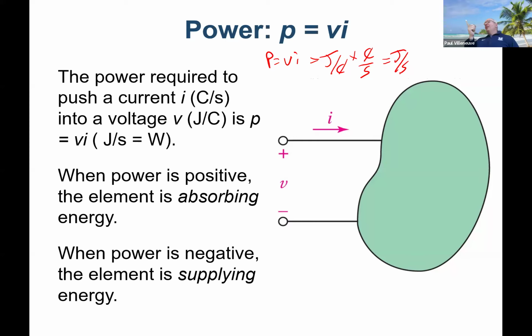We change the title. But is it a different motor or is it the same? Is it the same piece of machine or is it different? Same machine. So you can have that machine, we'll call it a machine because it's a generic term. That machine can either act as a load, like when you're accelerating and trying to get the car up to speed, or it can act as a generator and suck power and put it back into the battery.